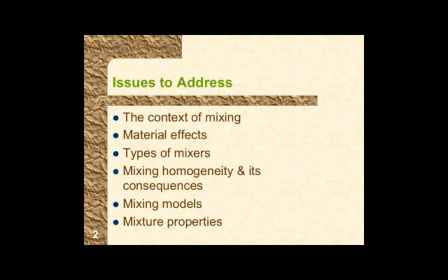So controlling rheology, on the one hand, you want to fill it fast enough, but you also want to make sure that it doesn't lose heat too rapidly. So thermal conductivity, heat capacity is the reverse, right? Ability to hold heat; thermal conductivity is the ability to lose heat, right? Those have to be balanced out in a mixture. So these kinds of properties become important. And then depending upon the nature of the process, just like in chemical engineering, you deal with PVT, pressure, volume, temperature relationships, when you're dealing with liquids and gases. You have to deal with those properties when you're dealing with polymer mixtures as well.